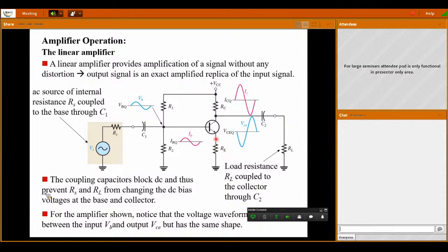As well as we should also connect one more capacitor, which is called the emitter bypass capacitor, in shunt with RE. So this is the capacitor connected in a CE amplifier. CE is the emitter bypass capacitor. So with the connection of these three coupling capacitors at the base, collector as well as emitter terminal, in addition to the voltage divider, we can form a CE amplifier.